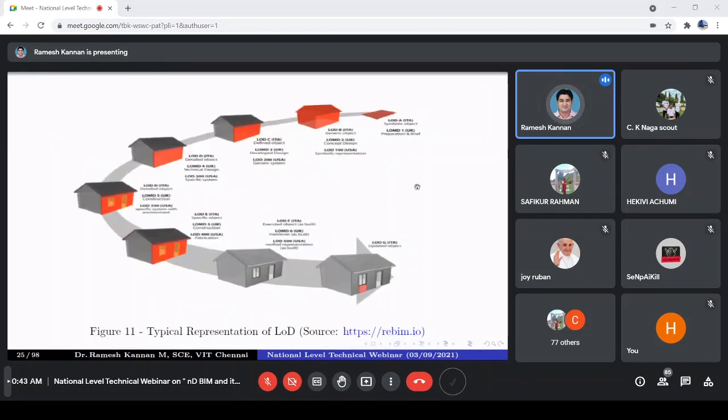So this picture illustrates an LOD 1, or LOD A in terms of the Italian perspective. As the LOD number increases, the buildings become more comprehensive and detailed. It has just a layout, then just a geometry, not even appropriate geometry, vague geometry. Then a defined object. Then up to here you can see specific objects or fabrication, and this is a specific environment condition, construction, this LOD 5. Then LOD 6 is almost more detailed. And this is the final one, LOD 7, which is very detailed, with huge updated objects or something like that. So this is how the levels of development or levels of detail are.